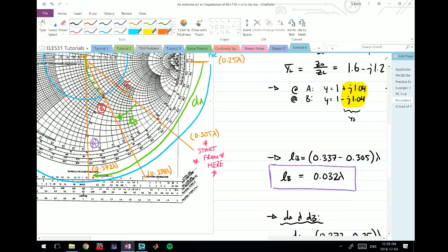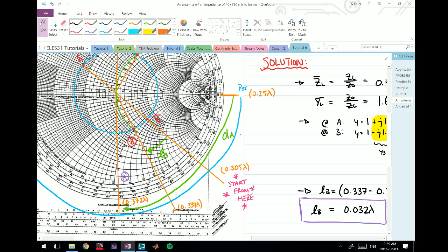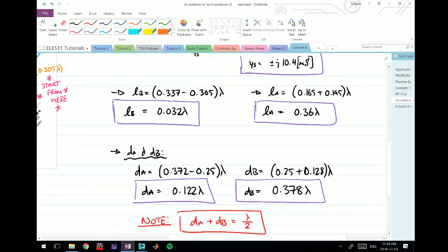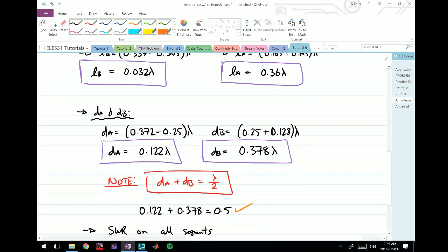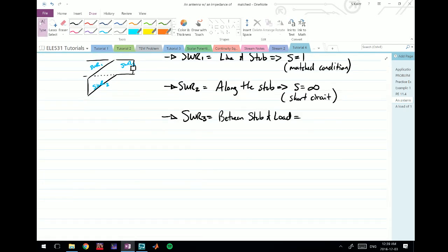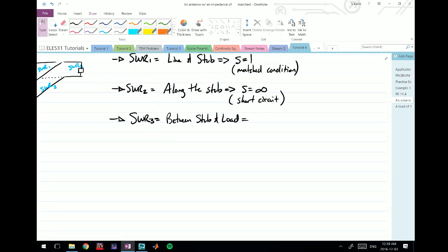Now this is the one that we can actually find without just reasoning what's going on. For that one, we go back to our Smith chart technique and we find this point where it intersects here. Now if you find that point where it intersects, I believe I see about 2.6. Should be a little bit higher actually. On my paper I have about 2.65, closer to 2.7. But according to this one, we'll call it, let's say, 2.65.